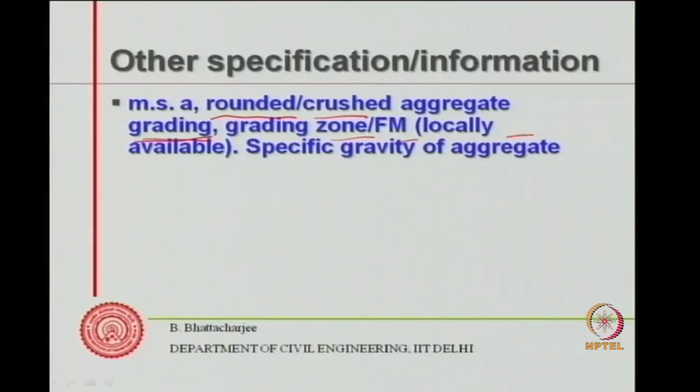So one would like to use locally available aggregate, and therefore what are the size fractions available. If there is anything missing, such informations would become important in mix design. But we have already seen how this MSA affects the packing characteristics of aggregate, how shape of aggregate affects the packing characteristics, and its effect on fresh concrete, etc. We'll understand, of course, later on.